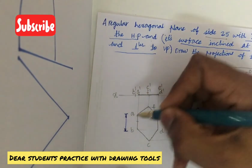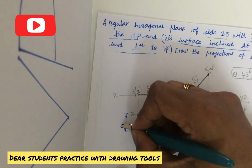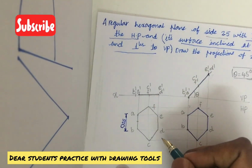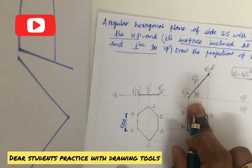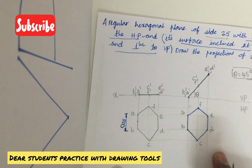Make sure your arrowheads are very neat, and draw a small symbol of hexagon so that it indicates that all sides of the given hexagon are 25, and do not write 25 throughout the hexagon, only on one side of the edge. And do not forget writing even the value of theta, that is nothing but 45 degree, and write a note: hexagonal plane inclined to HP.